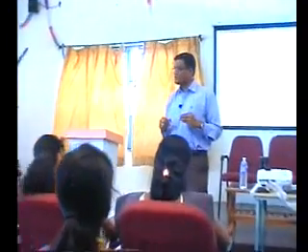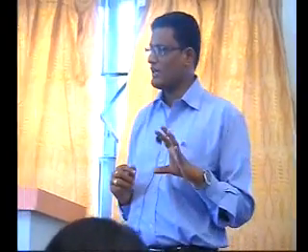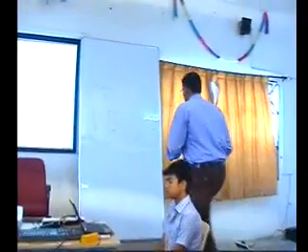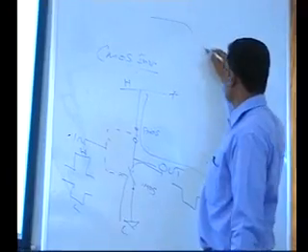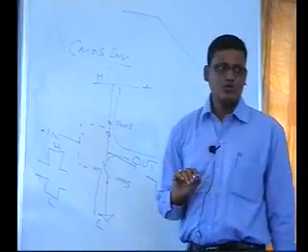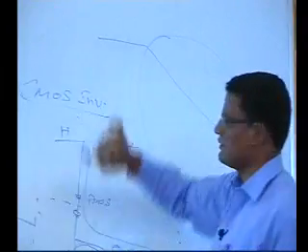Again in textbooks, if you carefully see, you will have a diagram called DC characteristics or transition characteristics. If you look at this on and off state transition, for example, you are designing a CMOS inverter, right? If you use only NMOS transistors, this particular gap will be more.